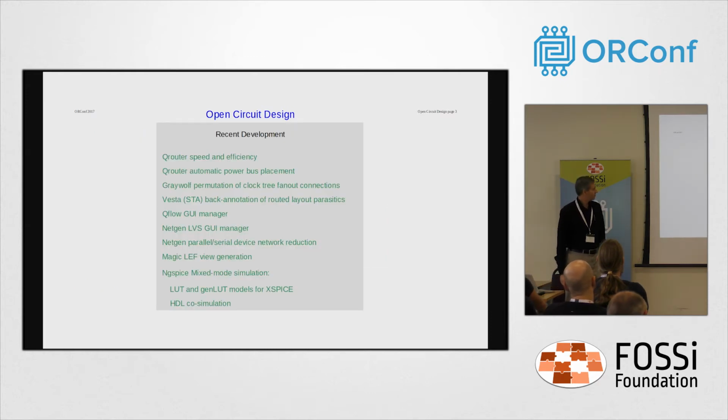So here's a little bit of recent development. I'm going to say that what I've described is basically end-to-end. You can figure out all the pieces that you need for that, right? It's placement, routing, static timing analysis, and generation of GDS. And a few other things in there, clock tree. All the things that are given to you, you take for granted when you're doing an FPGA. What about the clock tree? Well, the clock tree has been installed for you already.